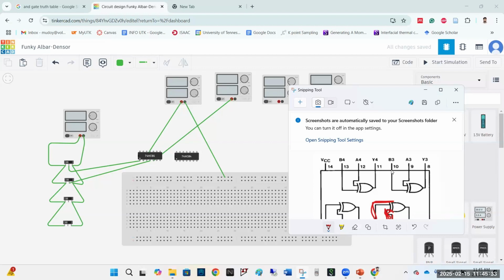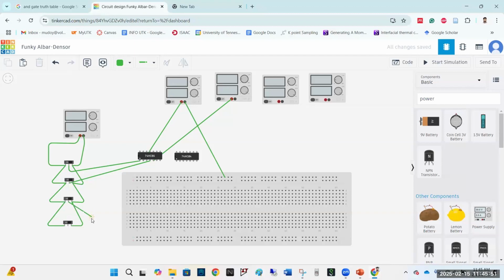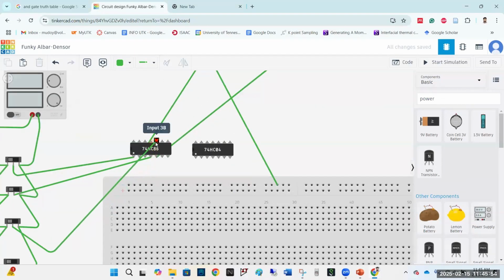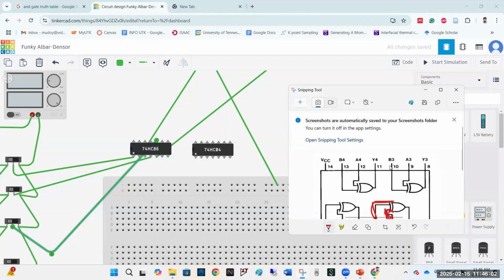So by observing this pin diagram, you have to connect the ICs actually. So the first input, I have moved to the third XOR. The third XOR's first input would be the input from the switch, right? I mean the user switch. So I'm connecting the user switch to pin number 10 of the IC. In this way, this pin is connected. The third XOR's first input is connected through the IC.